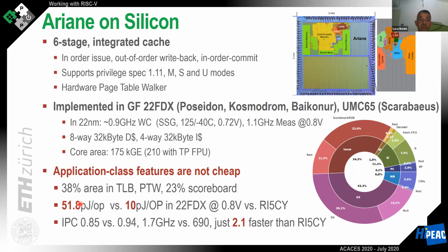So same technology, energy per instruction from a microcontroller level core to an application level core, the cost in terms of energy goes up by a factor of 5 to run sequential code. And remember, this is not speed, this is energy. So it's power multiplied by time.